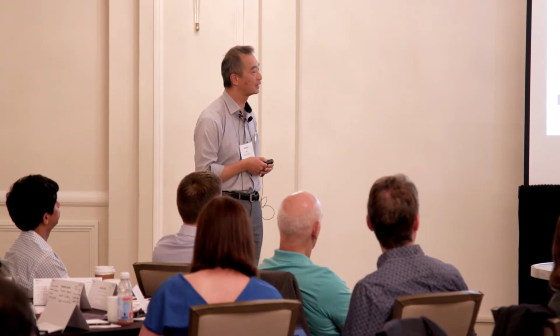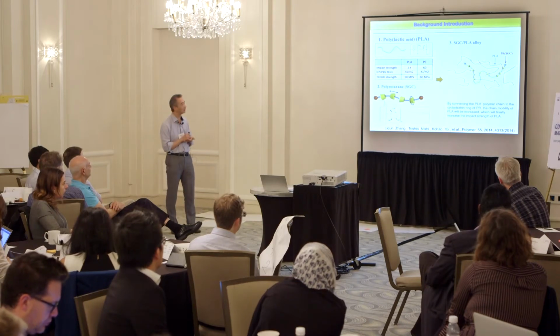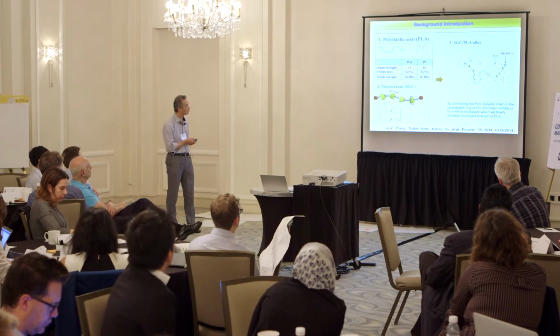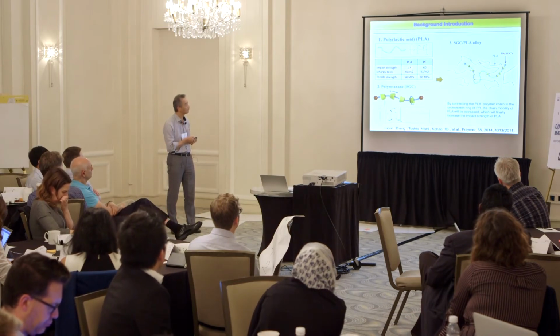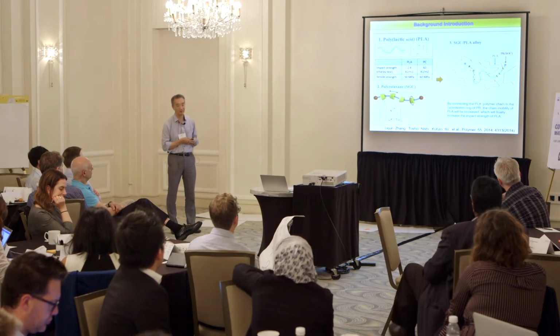Okay, next I'd like to show you the application of sliding materials to polylactic acid. Polylactic acid is a bio-based and biodegradable polymer. It shows a high transparency and high Young's modulus. But the drawback is the brittleness. It shows a very small impact strength compared to polycarbonate.